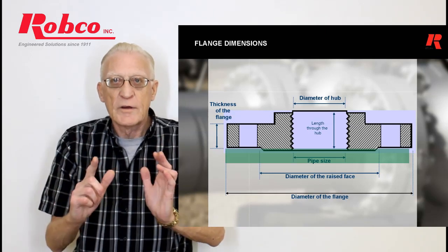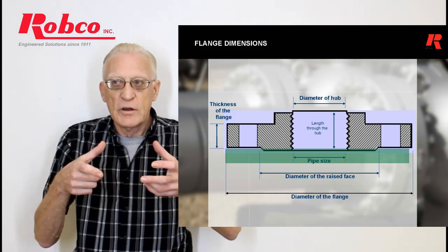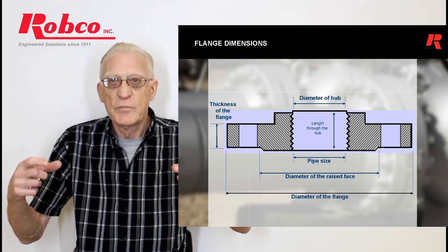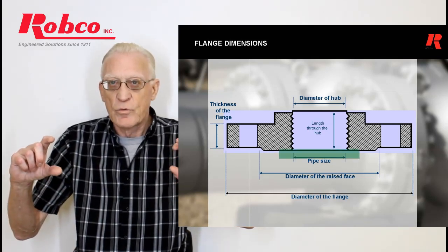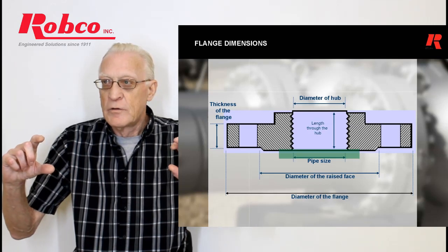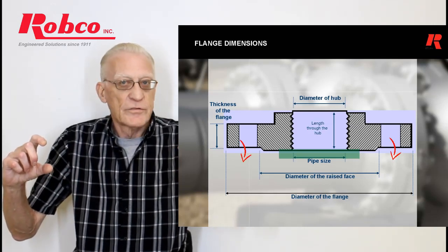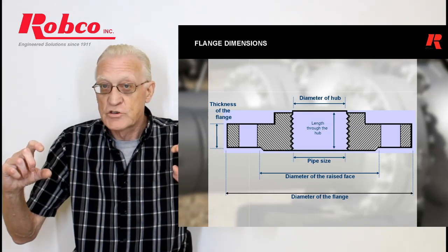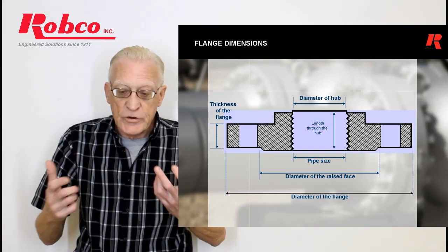If you put a ring type gasket in near the ID of the pipe and the area in between the flanges where the bolts are is empty, you're going to pull from either end and cause breakage, essentially, or what they call flange rotation or warpage. So that's the two different things.